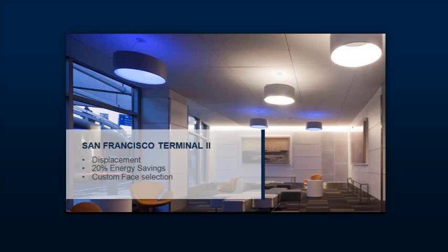And above this magic line, we start letting the air stratify more thoroughly. The idea is that I'm not taking any heat from the upper levels back down into the breathing zone, nor am I taking any contaminants back, say the cough from your coworker or the sneeze. One reason that I've seen underfloor used before is that you can incorporate the building services in the floor. And I've actually seen several jobs go together weeks to as much as a month faster than what they'd originally estimated, because all of the contractors have full access and they don't have to get in the way of each other like you do sometimes in overhead systems.